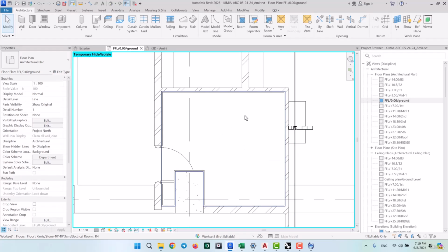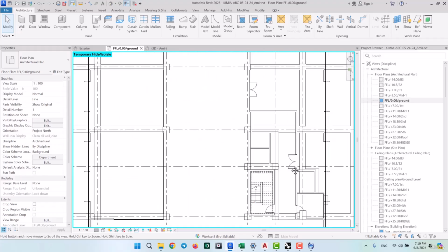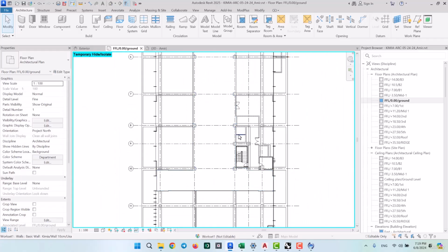If you have a ceiling in the area, then the wall would have to go up to below that ceiling. You could also have it on unconnected mode, or you could just set a negative offset to the wall's height and make it something below the ceiling's offset. So you're just going to have to adjust the height or fix it if you need, and therefore you will be finished with the flooring and creating the finished walls.